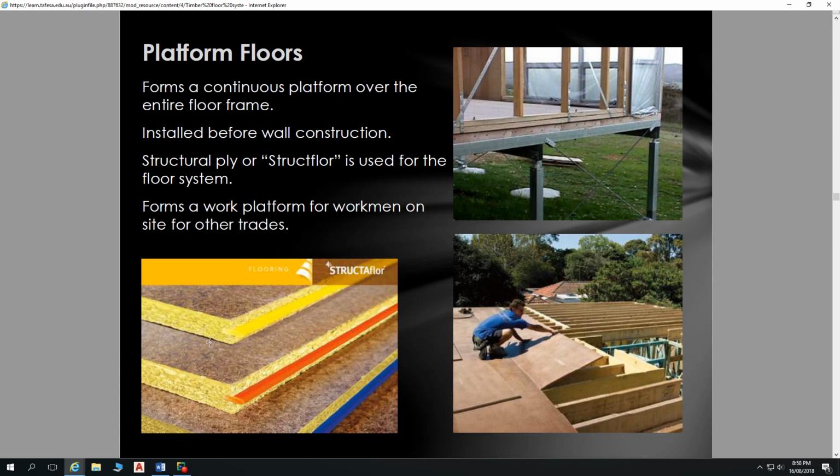Those floor sheets needed to be replaced, but because it was a holiday house, it went unnoticed. The floor joists, which are engineered beams, got affected. That's incredibly expensive to repair, simply because of the wrong specification of a material. If they'd used a thicker sheet, it would have cost them 20 or 30% more to build that balcony.